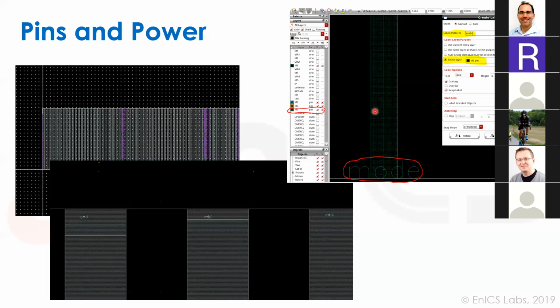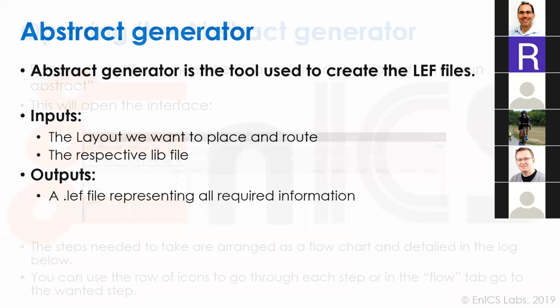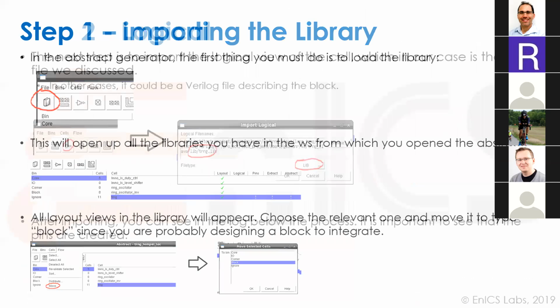So this, I think, answers what Slava was mentioning before. From what I understand, the methodology should be that you need the metal 3 drawing, or else you don't actually print out a piece of metal 3. But on top of the metal 3 drawing, where you want the actual thing translated into the LEF, you should have a metal 3 pin that is exactly on top of the area that you want to be exposed to the abstract generator, and you should not be translating any drawing layers. You should only be translating pin layers. Exactly. The X that you're talking about is there, you just couldn't see it.